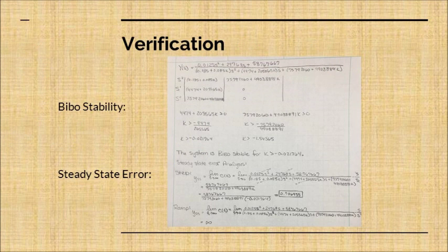Based on the Routh-Hurwitz analysis of our transfer function, the system is stable for a K value greater than negative 0.021764. Through steady state error analysis, we found our step input value to be approximately 0.79 and our ramp input value to be infinity. This tells us that our system cannot handle a ramp input error but can handle a step input error. A higher DC gain would give us a step value error closer to 0, which would give us a higher accuracy in response to error.